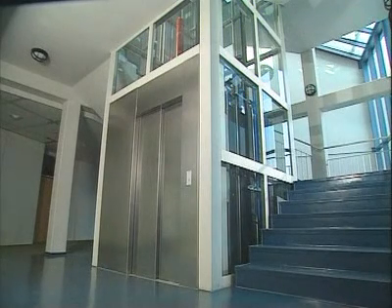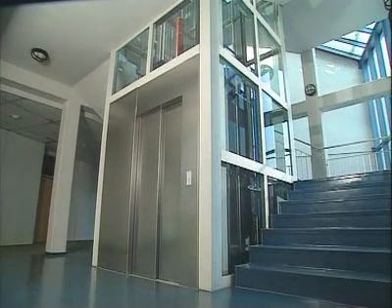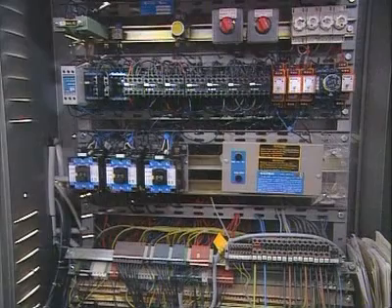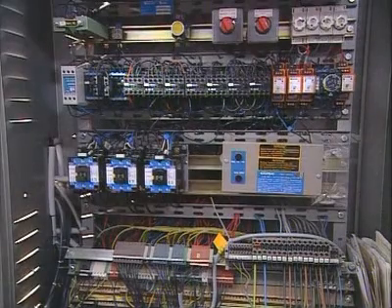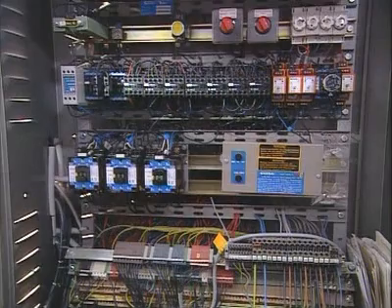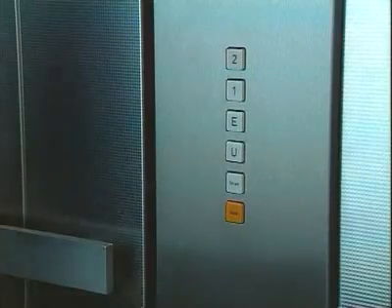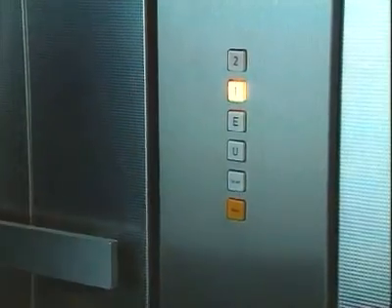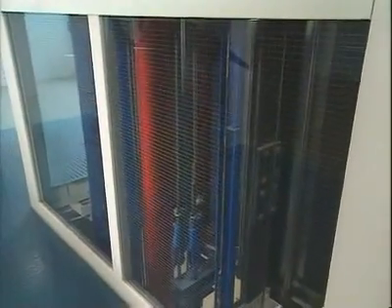In this elevator, we can see hardwired logical associations for the control of the hydraulic power part. The elevator only travels when the push button has been pressed and the elevator door has closed. This is a logical AND.